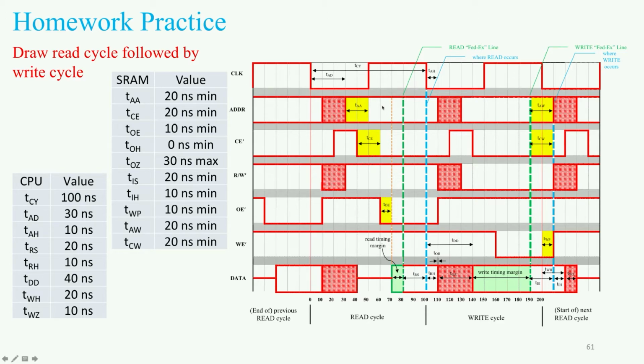Well, it's the same as the address hold time that occurs on the read for this read cycle. If you're looking just at the numbers here, you first look at when the clock falls, and we're just looking at the address line. The hold time is 10 nanoseconds. So you know that there's 10 nanoseconds between when the clock falls and when the address starts to go into a state that is potentially unknown. This crosshatched region is the unknown time.